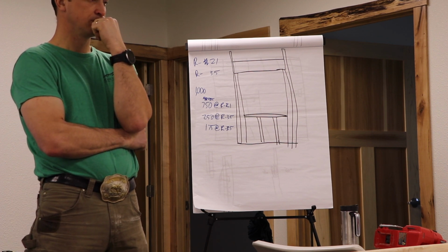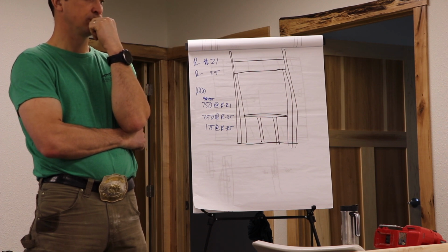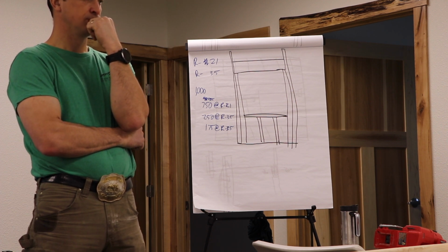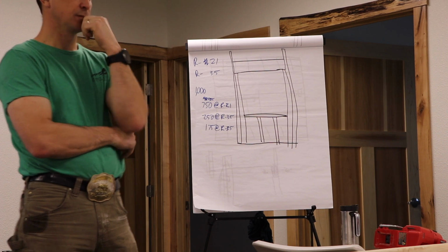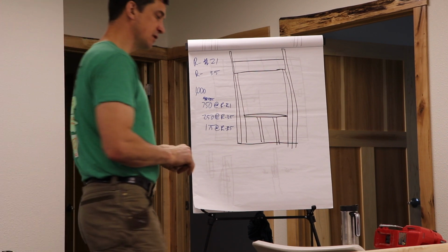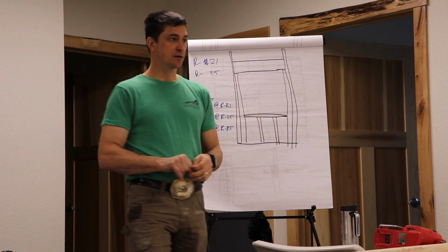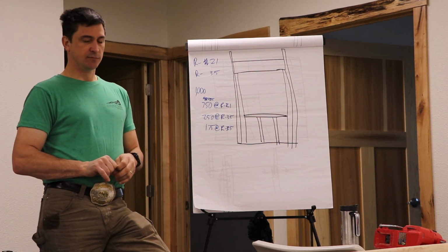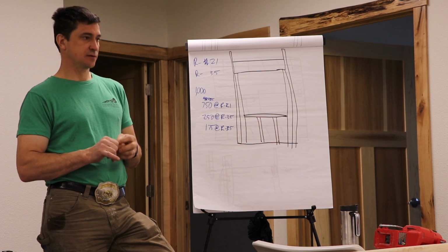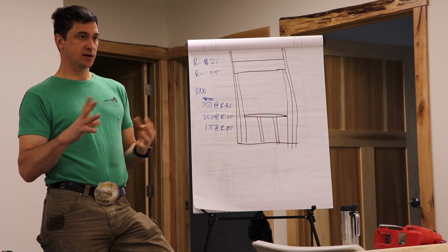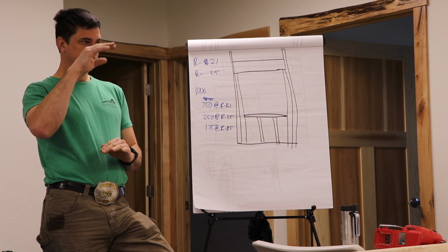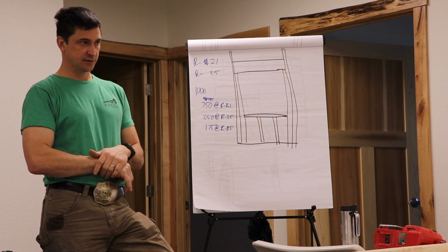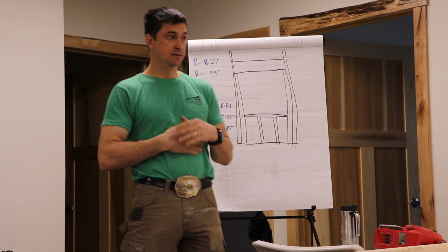The frost was melted on the steel, and everywhere else where it was spray foam insulated, there was still frost there. You'll see it all the time. It's not so dramatic when you have a truss that's insulated, but when you have a rafter that goes all the way through the insulation, it's dramatic.